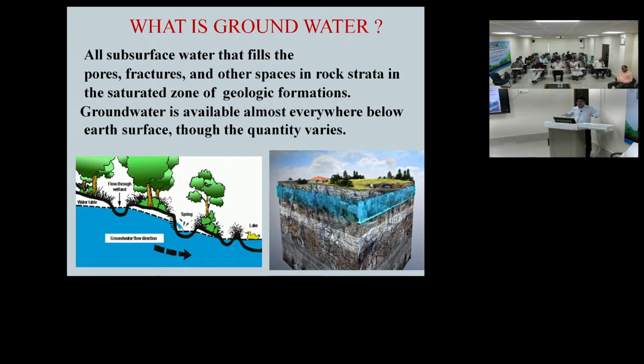Not sediment exactly, you can say it's valley fill deposits, not like the sediments of the Brahmaputra valley, but deposits from weathering. In Guwahati it goes up to a depth of somewhere around 24 to 60 meters. After 60 meters we got hard rock, but we couldn't find a fracture until the depth of 185 meters. At 185 meters we got a very good fracture. The pressure was so high that we could not drill further. This type of thing happens because in hard rock areas it is very challenging to find water, especially for people from Meghalaya, Karbi Anglong, and even Guwahati, because Guwahati is a part of the Meghalaya plateau.